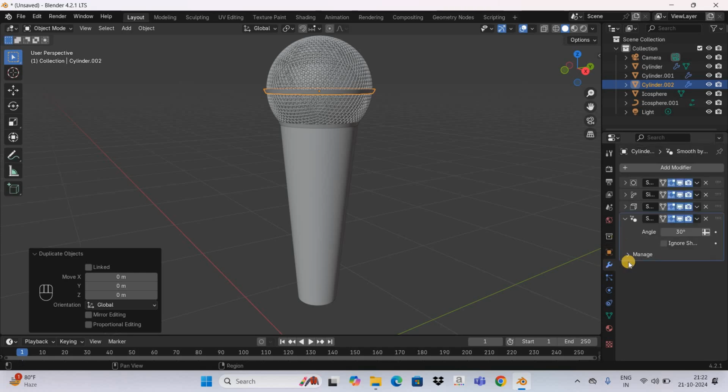All right. Now you need to add the simple deform modifier. So go to the modifiers tab. The simple deform modifier is already added because we duplicated the collar. All the modifiers which were applied to the collar are also applied to this duplicate collar, obviously. Let me expand the simple deform modifier. Now all you need to do is change the value inside the factor option from 0.040 to 0.030 and press enter.